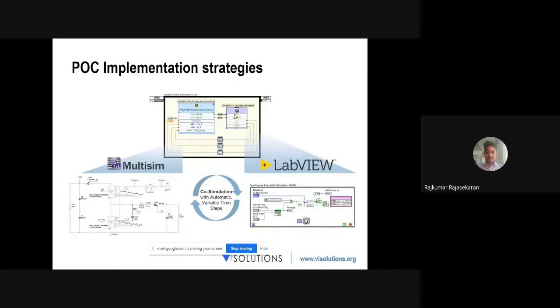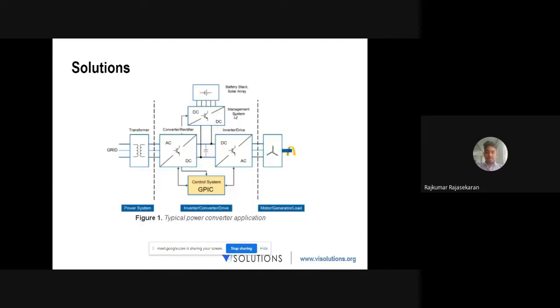Even though people say MOSFET is a voltage controlled device, even though it has a high impedance, it's going to draw a certain current due to the leakage capacitance between the gate and the substrate. So that current should be supplied by a driver. That's why we use a separate driver or an optocoupler, whatever is easy for you. So instead of doing this IO in a separate program, LabVIEW and NI's hardware platform is capable of doing it with graphical programming itself.